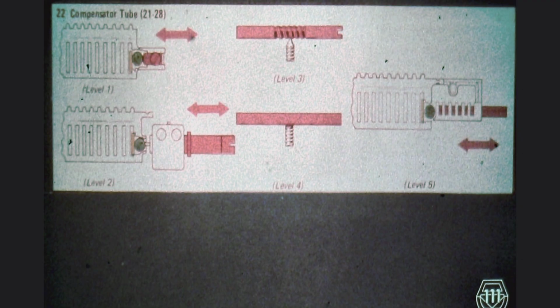When making this adjustment of the compensator tube, be careful not to force the interposers to rub against the edge of the rear interposer guide comb. Notice in the drawings that the depressed interposer is held against the right side of the slot in the interposer guide comb while the right plunger position is being adjusted. We must use the same procedure for the adjustment of the left side of the compensator tube.